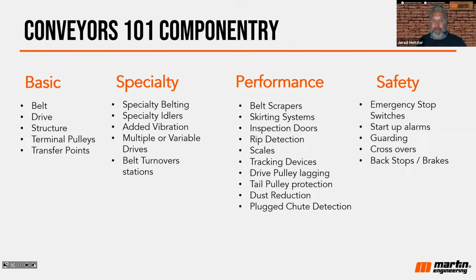Startup alarms, good practice to have a startup alarm to warn people when those conveyors are going to start up. Conveyor belt guarding, another really critical, important component that reduces injury around conveyors. And then crossovers for conveyors and backstops and brakes for conveyors are also considered safety components.